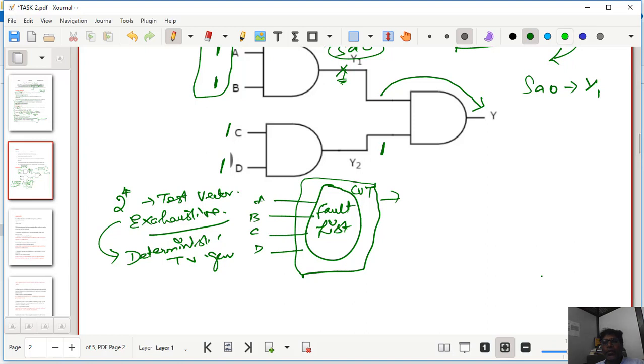The idea here is very simple. Say suppose I have 5 faults, this is the total fault list after collapsing by equivalence and dominance. So what I try to do is generate test vectors targeting only these 5 faults. I am just generating test vectors very specifically targeting the fault list which is available in my circuit under test.